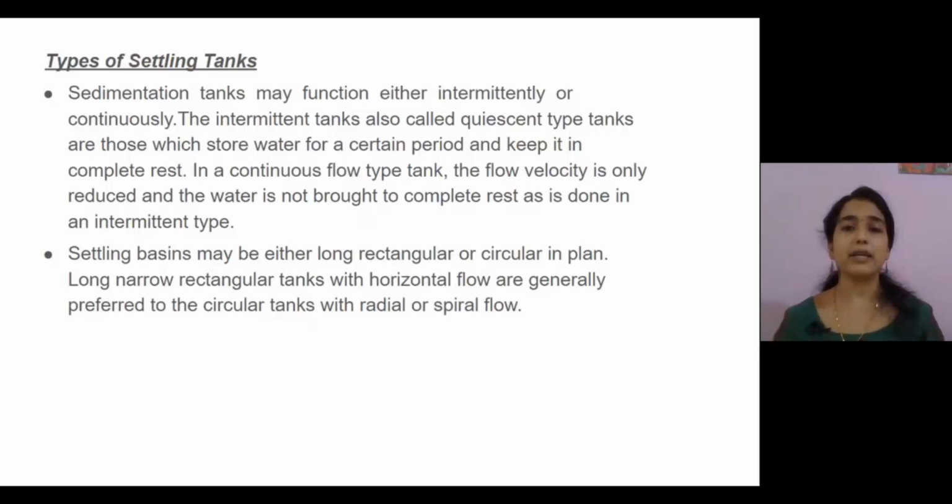The main difficulty with this process is that we have to provide an extra tank for the continuous treatment of the water, and we have to allow certain time for removal of the sludge from the tank, cleaning it, and then filling it with the raw water. This is obviously used in small water treatment processes.